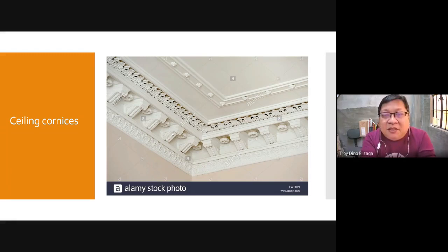But you can also do it on site if the design is just simple. No? What they do is that with the plywood, they cut the pattern and then put plaster and then just run that pattern over the plaster, so that creates that profile for the cornice.